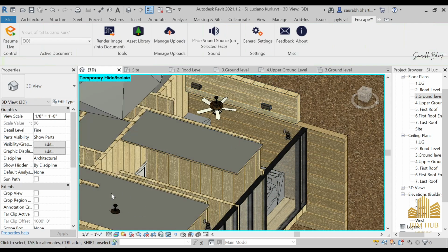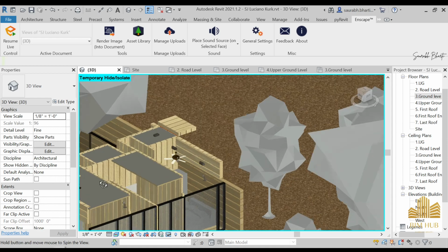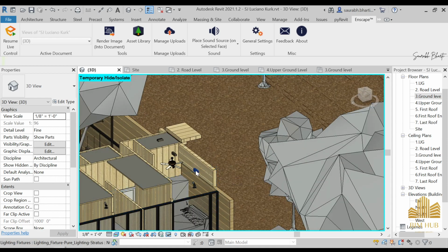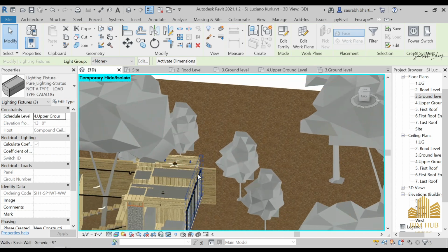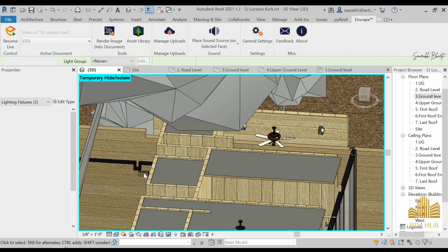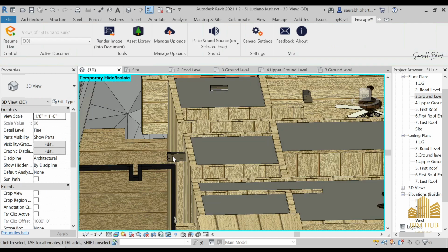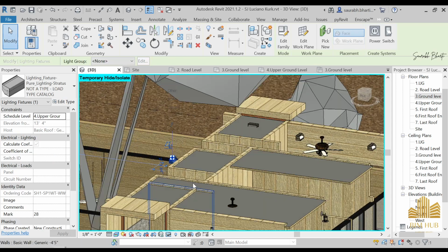And as you can see, whatever family we have on this side would have been flipped. So this is how you can flip it. And do we have it somewhere else? Spacebar to change its orientation, HR.